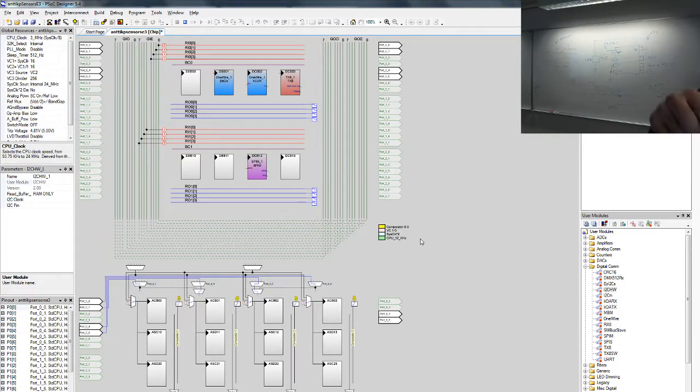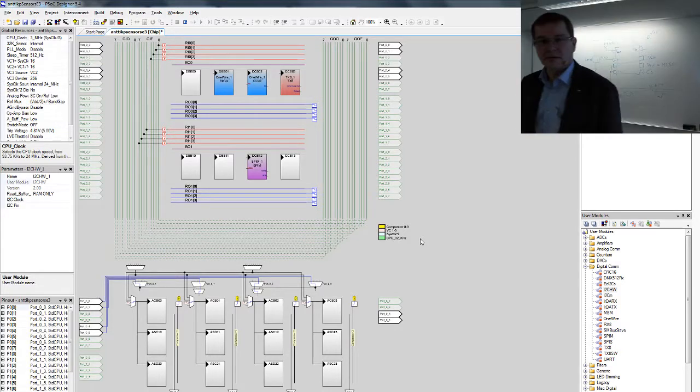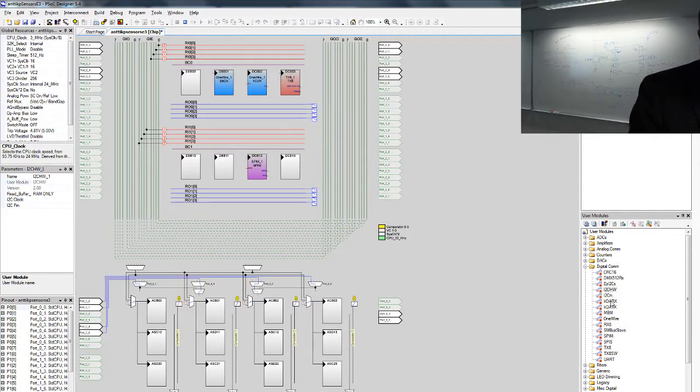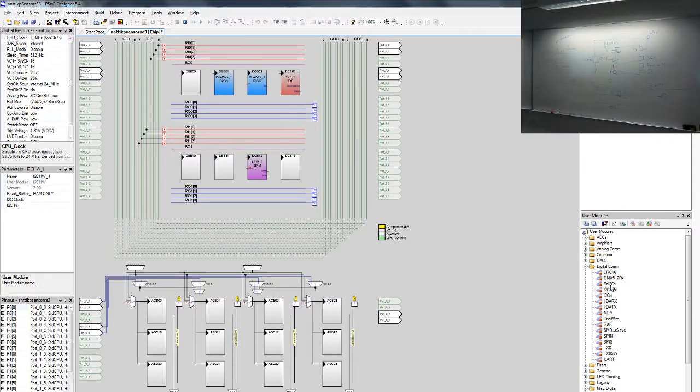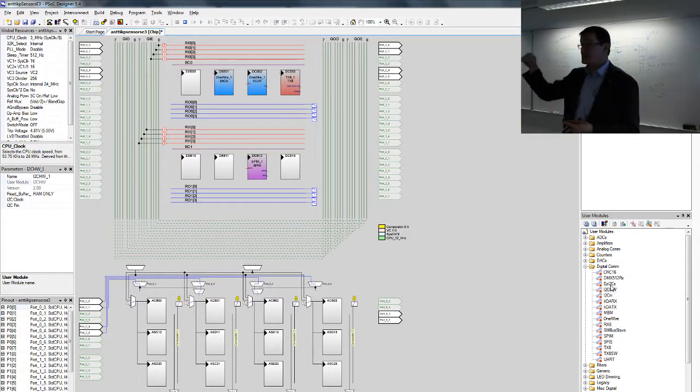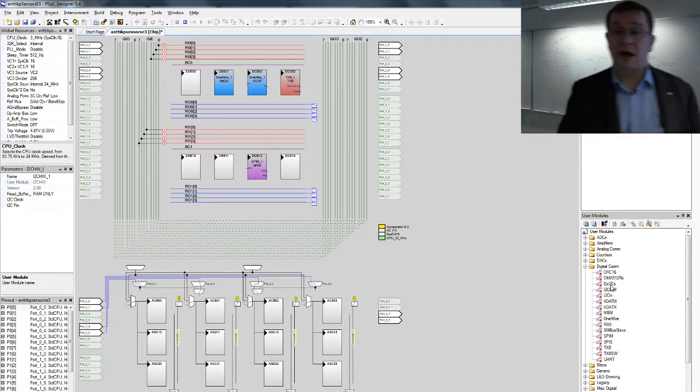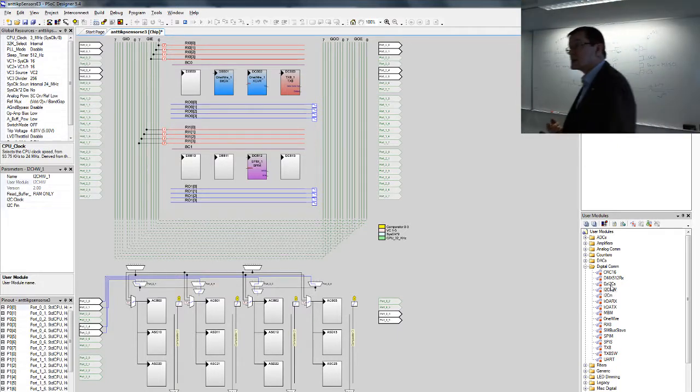So, anyways, any one of those I2C master kind of things. This easy I2C is basically how to make the PSOC circuit as an I2C slave device easily. So you can then set the address of this device and then access it from another device. Okay, that's quite nice actually.